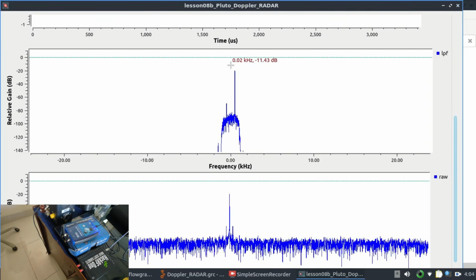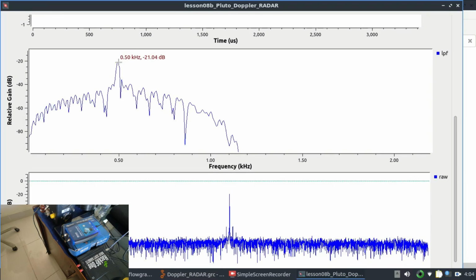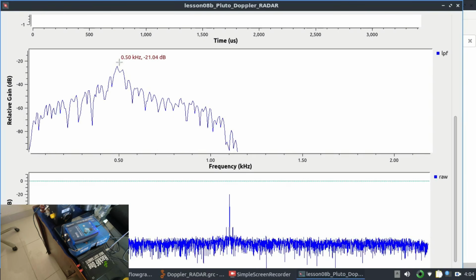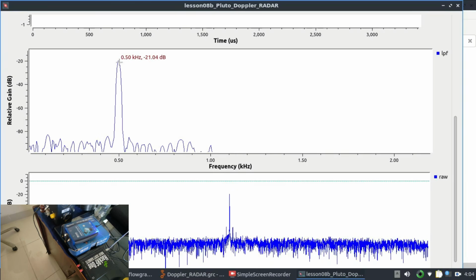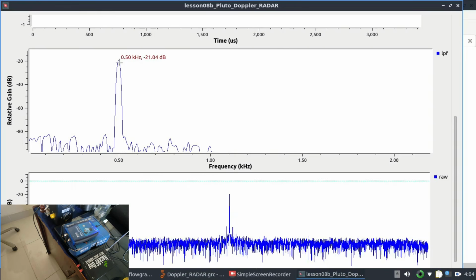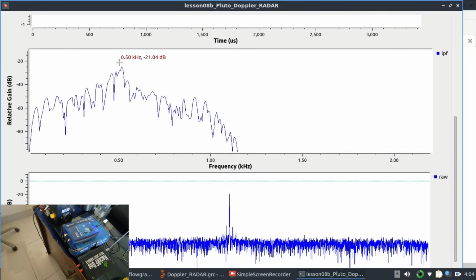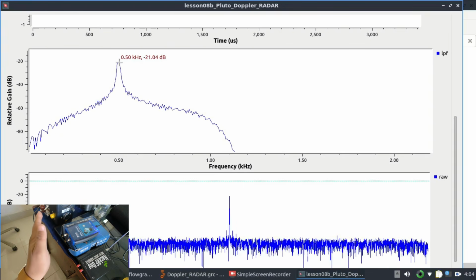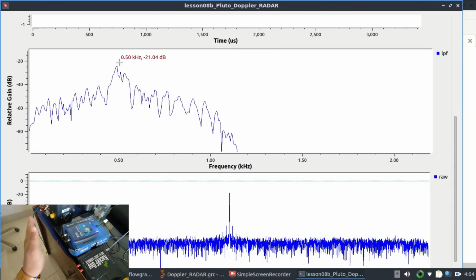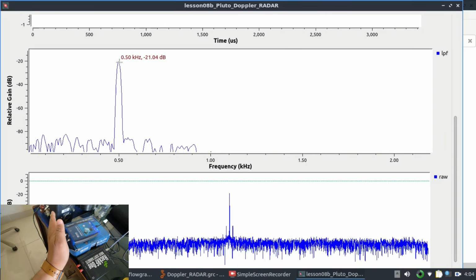So you can zoom in on it. This is what is being observed, and y'all can see this. This is around 50 kilohertz. This is what that low pass filter is doing: it's looking at only 1 kilohertz of signal, and after that it's only focusing on that, with a transition bandwidth of 250 hertz. When I move my signal, as you can observe, you will see a change in the graph as well. All right, you can see that as well.